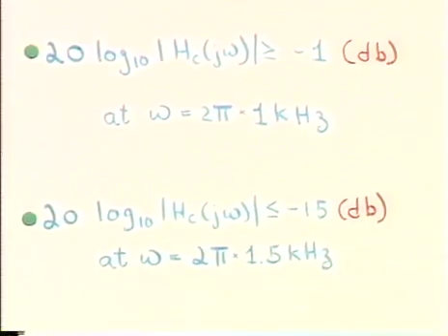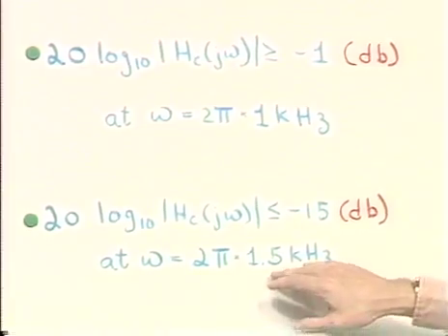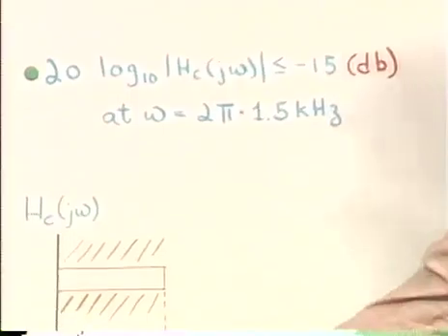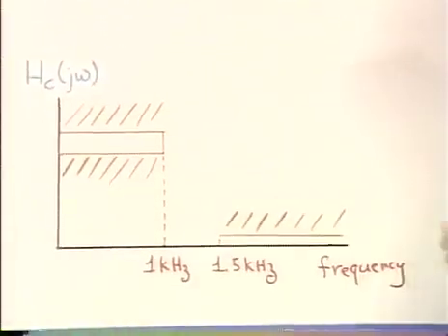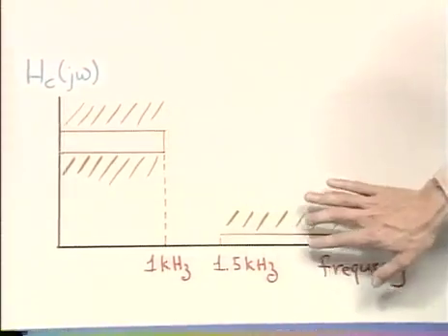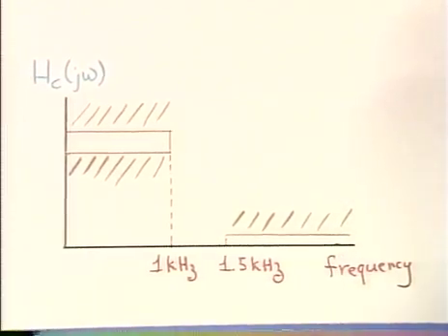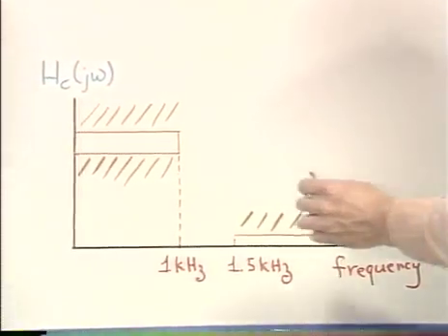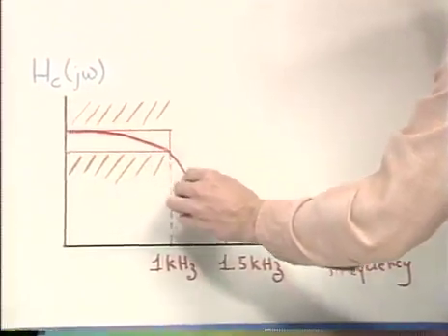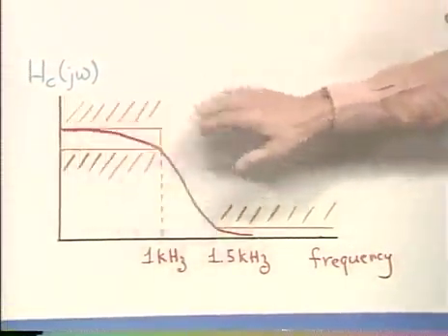And since we're talking about designing a Butterworth filter, we know that the Butterworth filter is monotonic in the passband and stop band. And so we'll have a filter specification, something as I show here. This represents the allowable passband tolerance. This is the allowable stop band tolerance. And if I can draw this without getting myself into trouble, essentially we're looking for a filter then that always stays between the specified boundaries here.